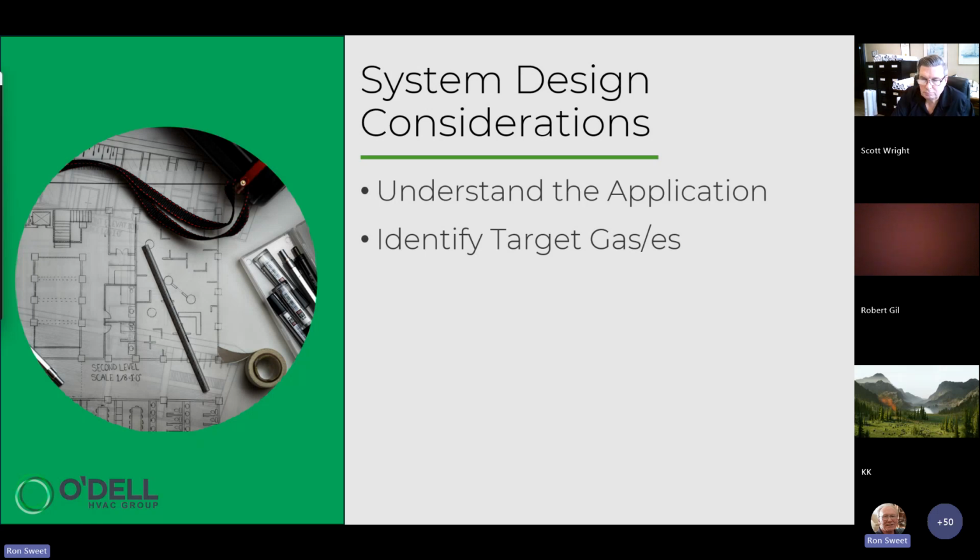because the chlorine generator needs to be monitored, versus a logistics center where the main gases of concern are carbon monoxide and nitrogen dioxide, from all the different vehicle activity within that facility and around that facility, including propane powered lift trucks and tow motors.